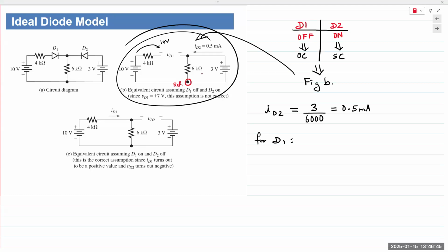Anode voltage is measured with reference to the bottom node, and cathode voltage can also be measured with reference to the bottom node. Because it's an open circuit, the voltage at both ends of that resistor is exactly the same. With the 10 volt supply connected at one end of the resistor, the voltage at the other end is also 10 volts.